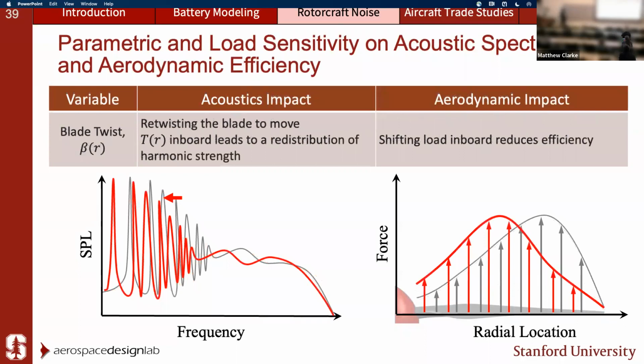that has low noise. And then lastly, blade twist can also reduce noise by moving the load inboard. When you're moving the load inboard, you're essentially moving the harmonics lower. And as I mentioned before, if you look at the A-weighting scale again, you have a more significant negative difference, right? So those harmonics at those lower frequencies will be reduced more in terms of human annoyance,